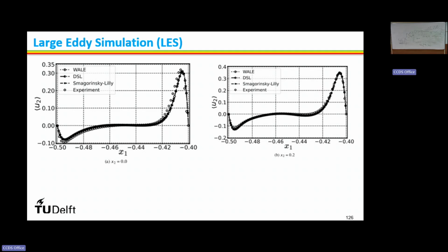Yes, this is definitely the filter length, how the filtration is done. The developer has defined some criteria to do the filtration, the averaging operator, right? Definitely that is different for the quad mesh, the triangular mesh, the prism shape mesh, or the poly shape mesh. But they are implemented in such a nice way in the code that we did not get any difference. Maybe different solvers have different implementation criteria, maybe OpenFOAM, maybe ANSYS, maybe STAR-CCM+, and different mesh structures may give you different results. Last time when I was discussing with the ANSYS developer, they too found this has a very minimum effect.